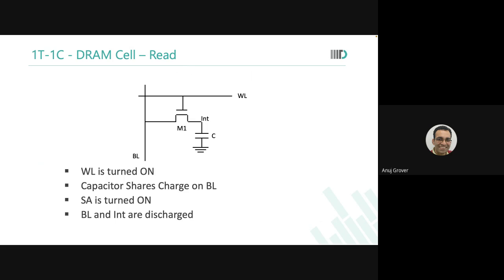Okay. How do you do the read operation? Again, you take the word line high, and once the pass gate turns on, it will couple its charge onto the bit line. And the bit line will go to 0 or to 1. And when that happens, do you also realize that I am continuing to write the same data back into the memory cell?